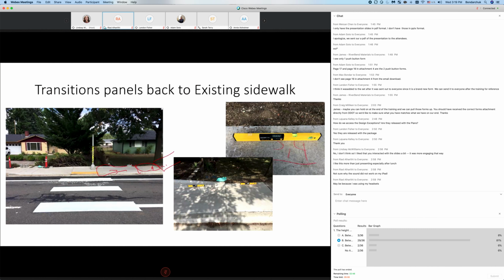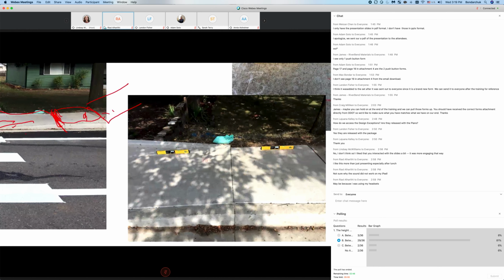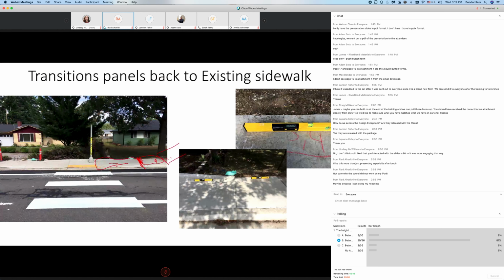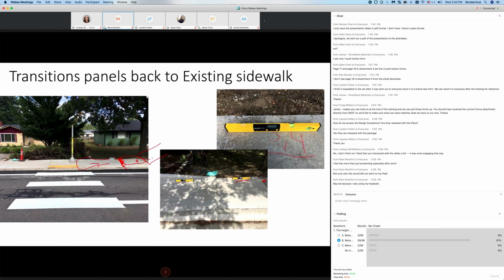So the cross slope may warp 0.5% per foot. The slope at the top of the ramp here should be 2%. It could warp 0.5% per foot to match the back of the slope here. And I can't read the slopes here, but probably the slope here and the slope here are not the same. Remember, x2 should equal x1, otherwise it will be an inconsistent ramp run.